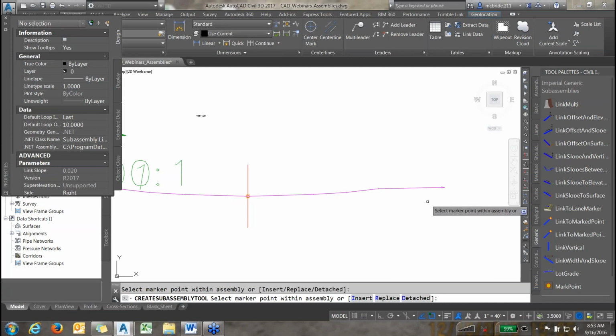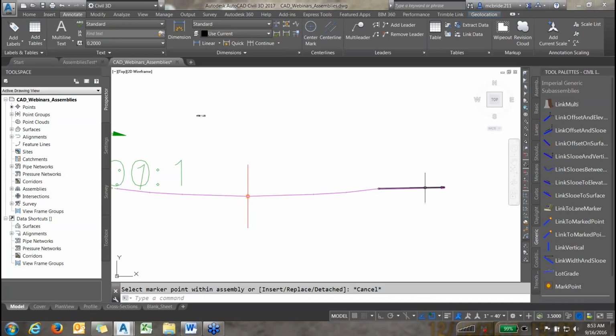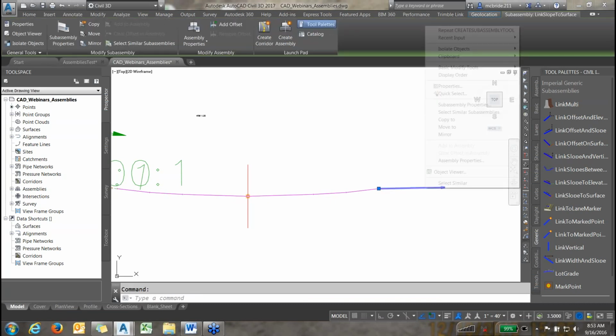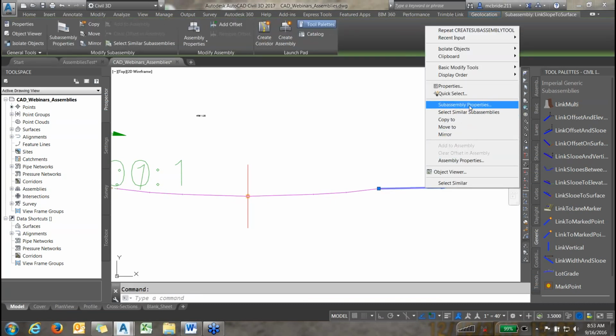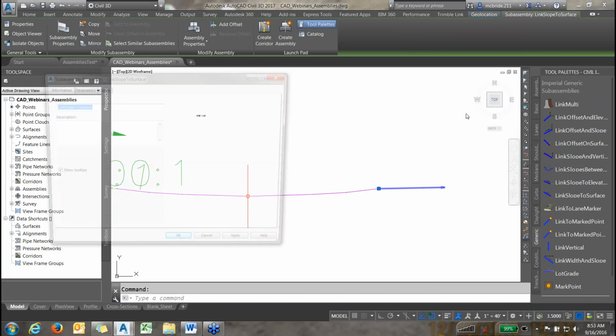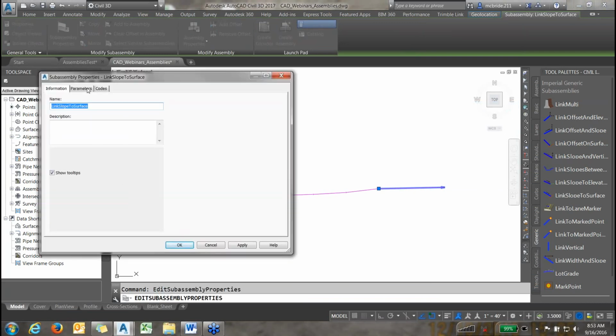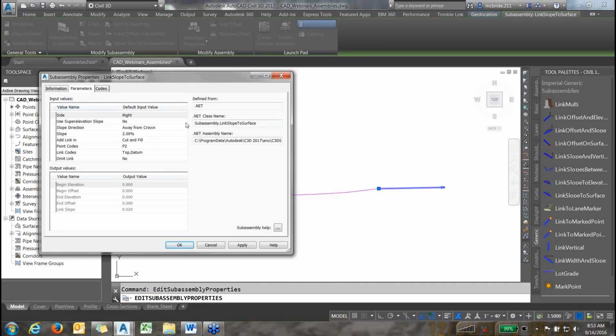Okay. I think the answer to that is you can change your cut and fill slopes and reaches if you want them to be different. Say you want to cut 4 to 1, but you want to fill at 10 to 1. Oh, yeah, that would make sense. See here in the parameters tab, there's only one slope, so it will seek the existing ground one way or the other, but it will only do it at one slope, so 6 to 1, whatever it is. But from what I did, you saw that I did two different ones. I did a 6 to 1 and I did a 200 to 1, and I'll show you why I did that here in a second.